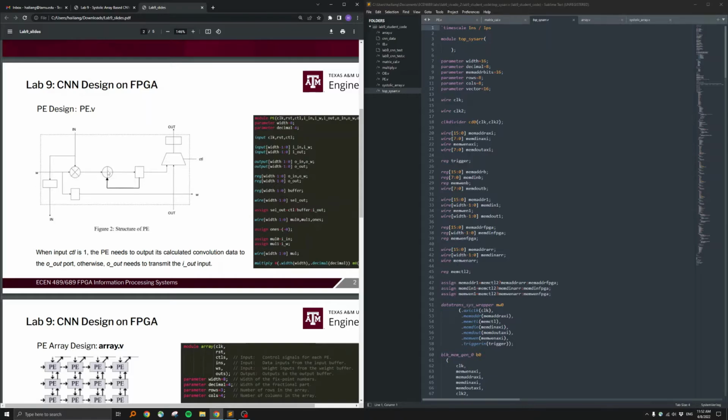And we will also do an accumulation, or summation, of the multiplication result with the previous result, which we save in a buffer here. Every time we have this multiplication, we will accumulate it with the previous output, and you can see the data goes back here. And then we can choose to send the value of this buffer to the output port here.